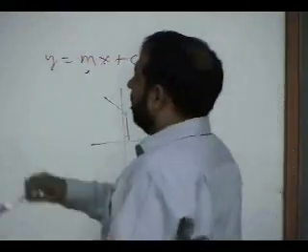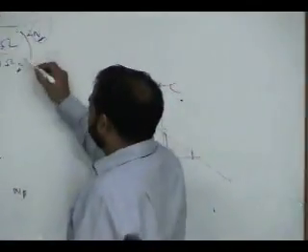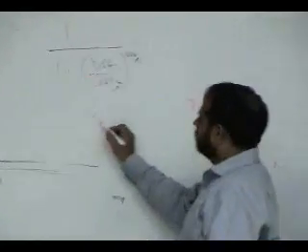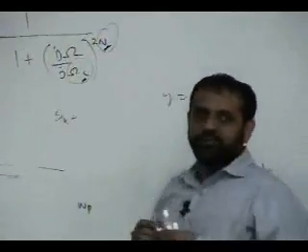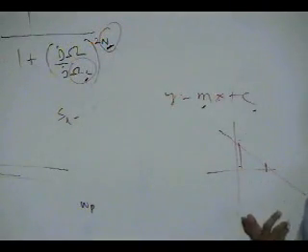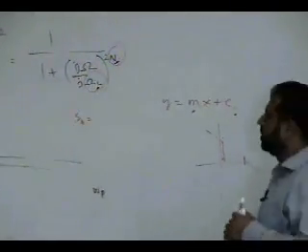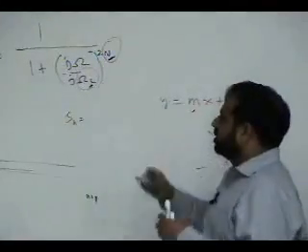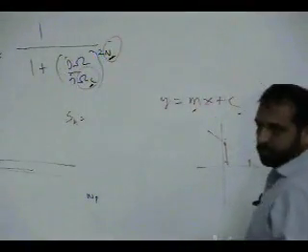So remember these are the only 2 design parameters. You need to figure out n, you need to figure out omega c, then you know the formula of all the poles. If you know n and omega c, you can plot the exact location of the poles, and that is what matters. So now it is a very trivial problem to solve.